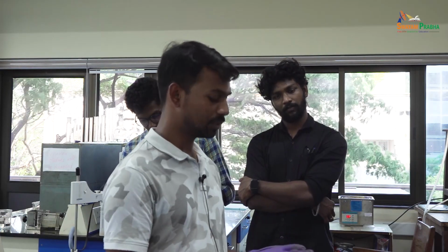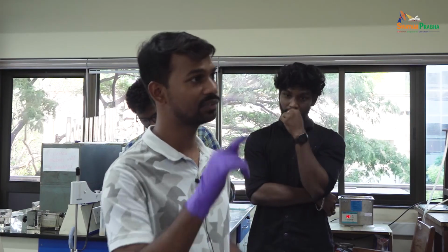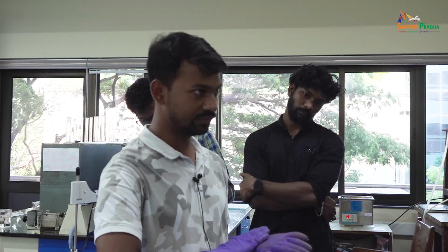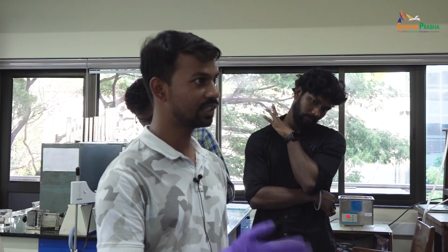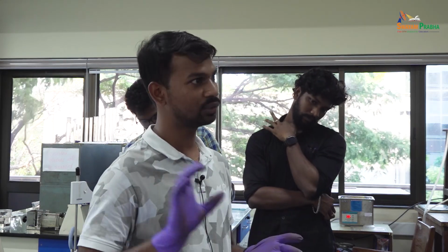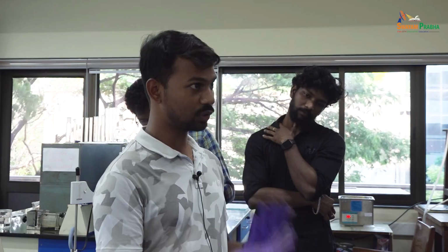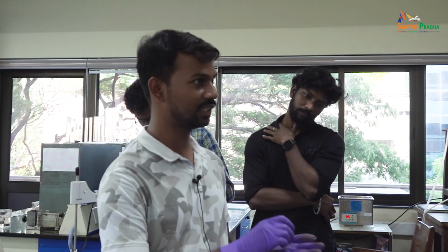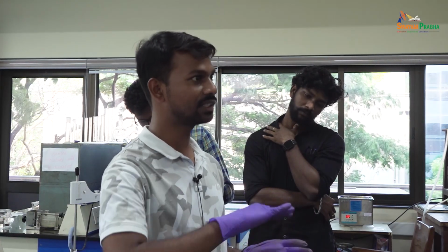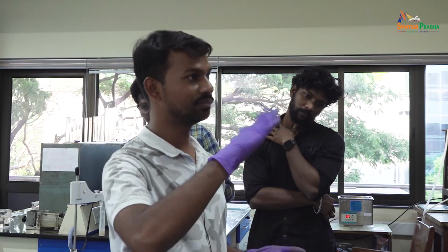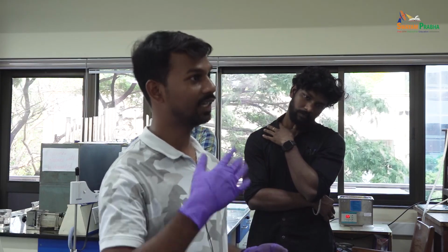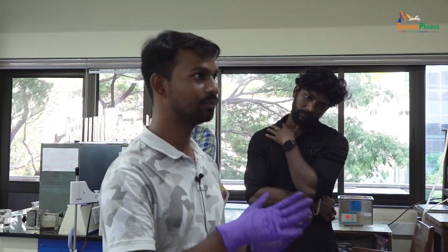See, porosity or surface roughness. Suppose what I am exposing here is around an 11 mm diameter circle. If it is very smooth, the area I am exposing will exactly match that circle. If there is porosity, which means the material is not there, or some surface roughness, which means it will have some ups and downs, in that case definitely the surface area will differ. So it will be high, and in case of porosity it will be low.